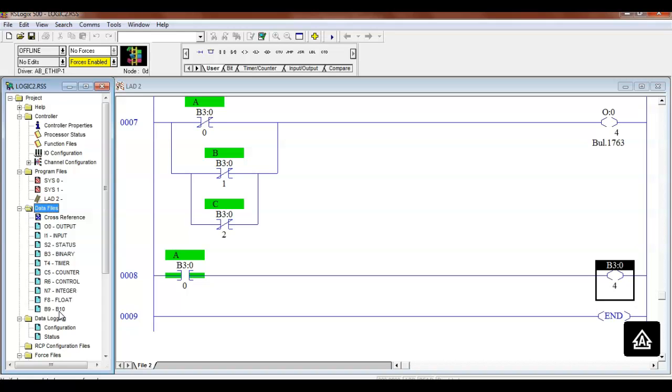So that's the power. So in PLCs, if the coil does not generate an output, if it don't need to turn on a light, if it don't need to energize a solenoid, if it don't need to turn on a motor, if it don't need to bring in a relay, then we'll use what? We'll use an internal coil. If it's got to turn on a light, or a motor, or anything outside of the PLC, we'll have to use one of our outputs. So every PLC I've ever programmed has the ability to use what? Internal coils.